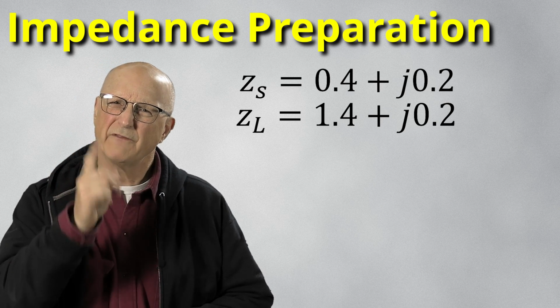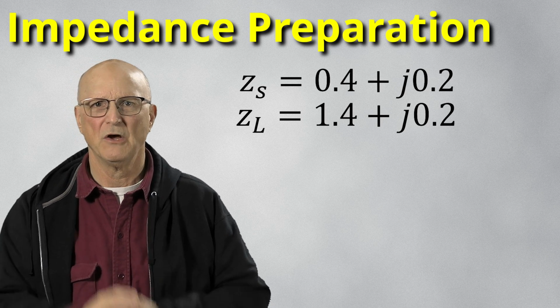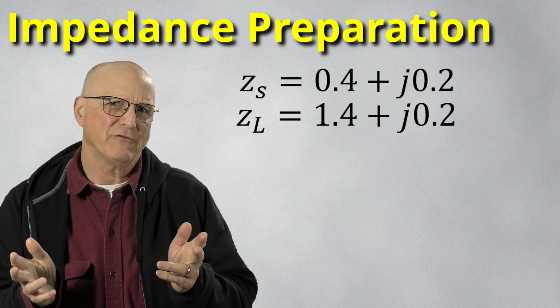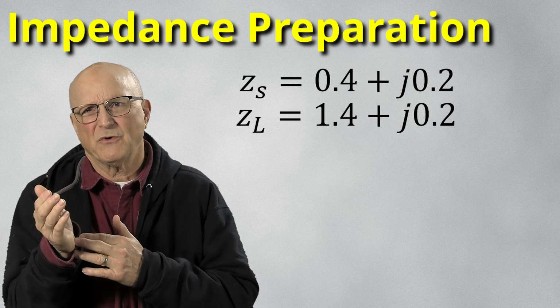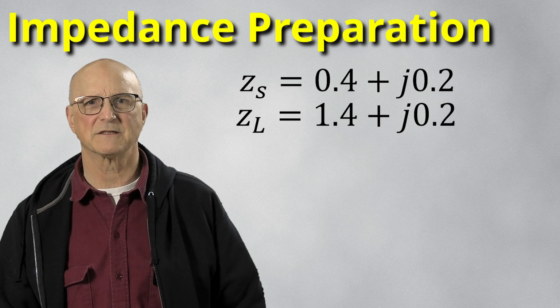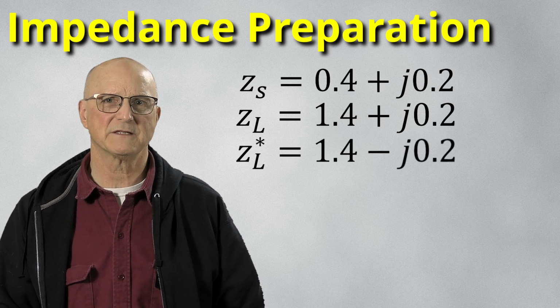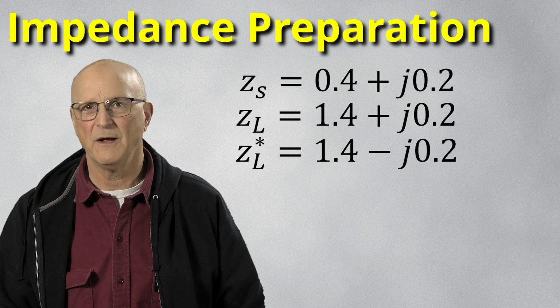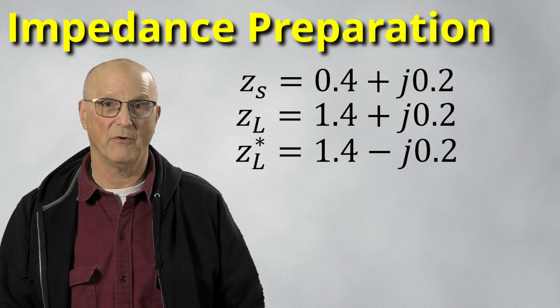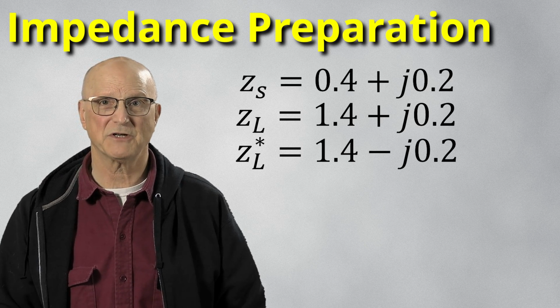So which one of these am I going to turn into a complex conjugate? For no other reason than it feels good to me to move from the source to the load, I'm going to choose the load impedance. The complex conjugate of the normalized load impedance is equal to 1.4 minus j0.2. Now we get to plot these on the Smith chart.